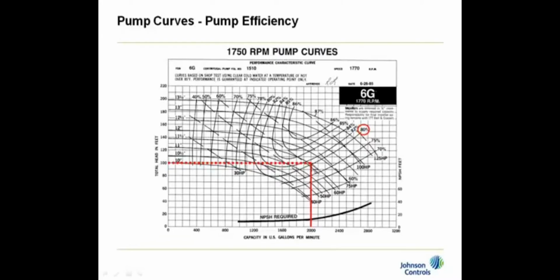And this will depend, of course, on where I am in my selection. But when I go to 140 feet, that we remember was our variable primary flow, then I move up to here on a 12.5-inch impeller. And now I'm up to 86% efficiency. Now this can vary how much this is. It sometimes can even go down, but most of the time it goes up, depending upon where you're selected versus BEP. If you're to the left or to the right, can change that.